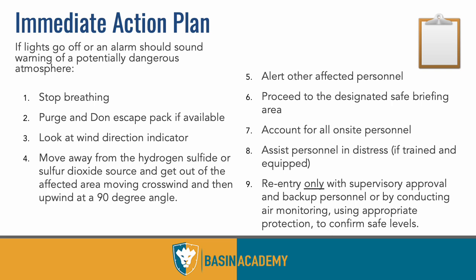Make sure that we understand wind direction, and my advice to you is always be aware of the wind direction on site wherever you are. Like, I'm upwind, I'm crosswind, I'm downwind of the wellhead, of the treater, of the tanks, wherever you are all the time. And then you want to move crosswind and then upwind, as we already talked about.